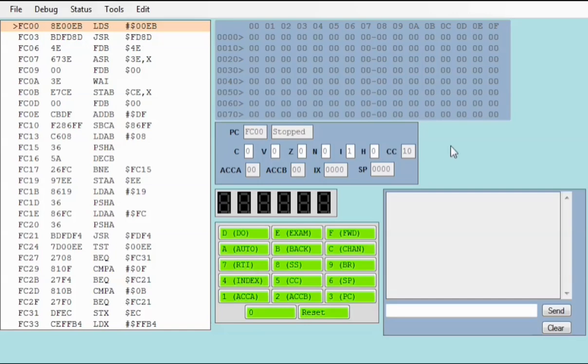What is contained in the expansion is it bumps RAM memory up from 256 bytes to 4K bytes. Woohoo! It also created some new memory address space for more ROMs. This has a 1K ROM to simulate the trainer, but with the expansion there are two more ROMs available. One is an advanced machine language monitor called the Phantom 2, and then there's an implementation of Tiny Basic.